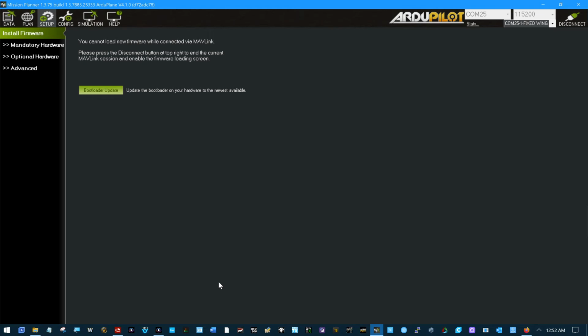I know that I can hook that RC receiver to my ESC without the flight controller in the loop and program a high throttle into that ESC of 2005 and a low throttle of 985 or whatever it is, and then take that RC receiver and set it aside and plug that motor back into that flight controller that's going to also give it those same numbers.